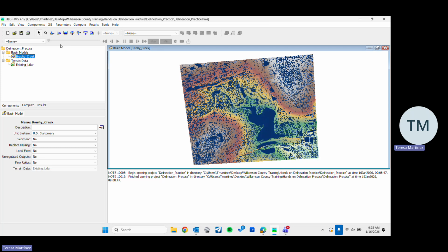So this step is essential: once we run through it, all the stream network will have positive connectivity, and the water will be able to get from any location in your basin, and if there's a connectivity to the outfall, the water will be ensured to travel to that spot. So that's the purpose of filling the sink.